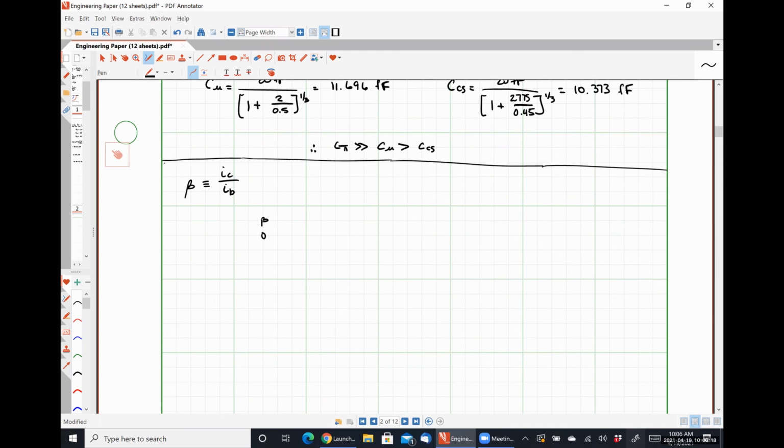So here is our base. Here's our resistor R pi. Here is our voltage V pi. Here's our capacitance C pi. Here's our capacitance C mu. Here we have gm V pi. Here we have R naught.